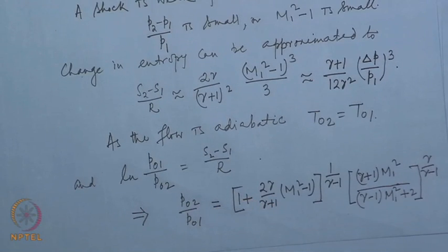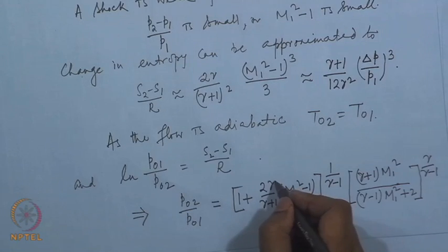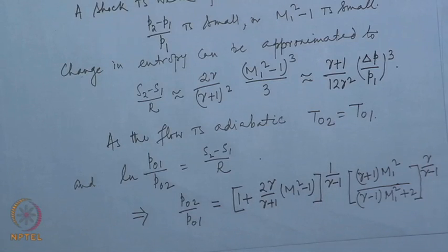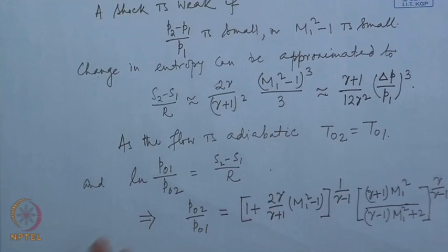Here the shock strength or shock jump relations have been expressed in terms of upstream Mach number. However, often they are expressed in terms of other parameters, particularly in terms of pressure jump instead of Mach numbers, and in general the shock jump relations are known as Rankine-Hugoniot relationships.